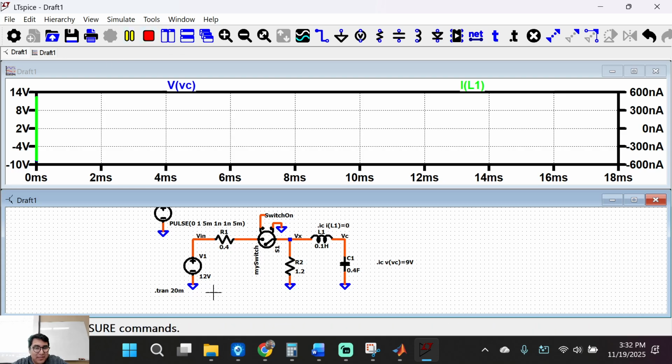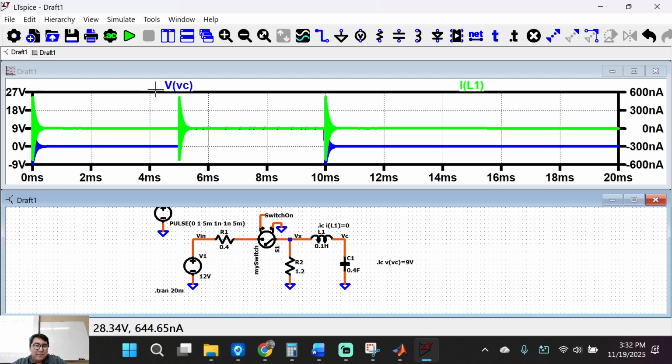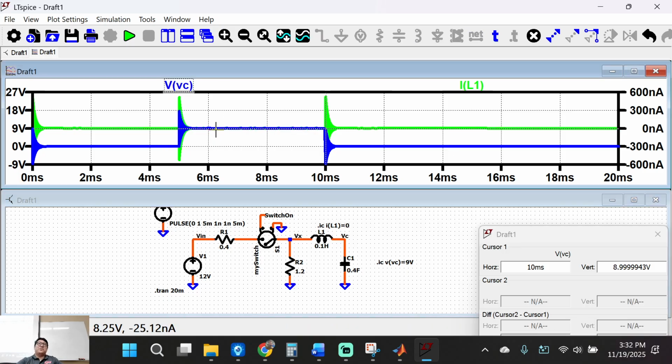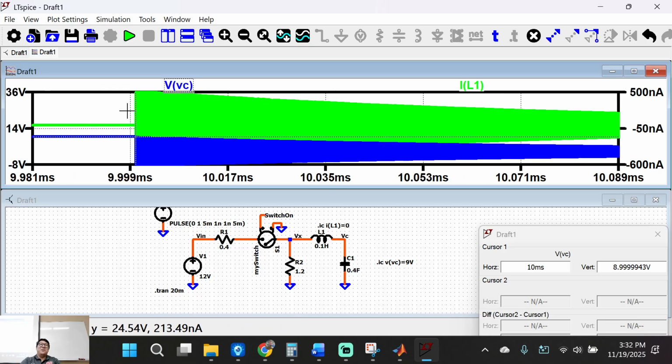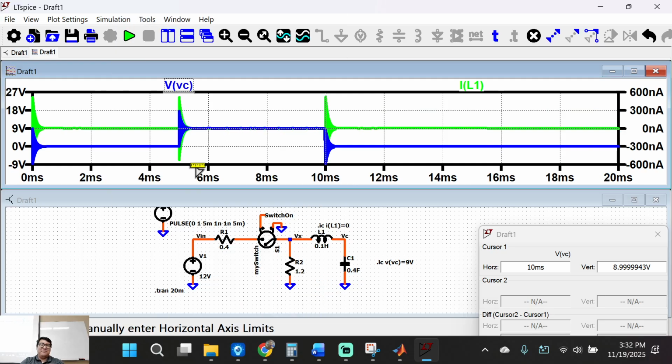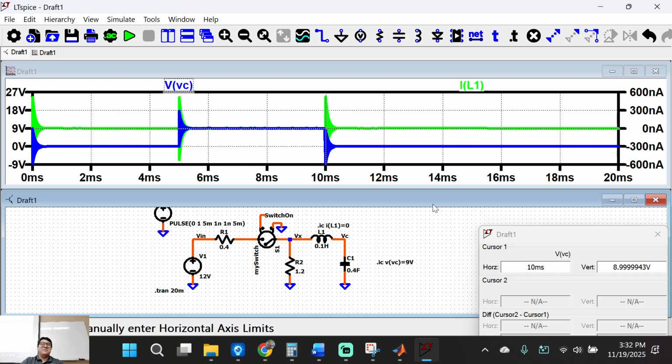Let me see. There we go. Okay. So let's explain. This right here is 9 volts, right? Our settling time, correct? Like, think of this as the switch is closed, okay? Now we open the switch and then it settles back to 0, right? We're seeing that overshooting, that overdamping. I think because this circuit is overdamping, LTSpice has to calculate all these little points. And you know it's going to be ringing, correct? Zoom to fit. Any questions? Yeah, I know. There's definitely an easier way to do this, but if this is what the circuit's doing, then so be it, all right?